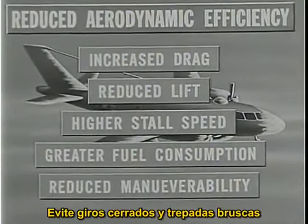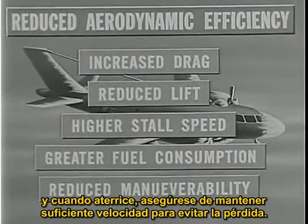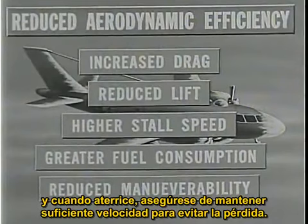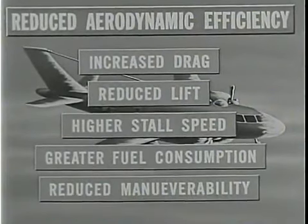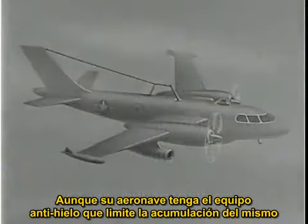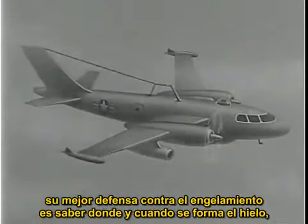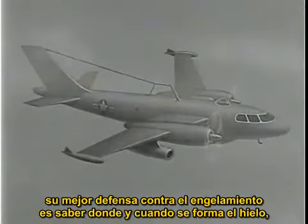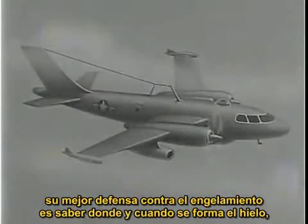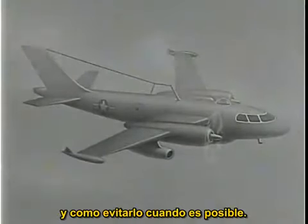Avoid steep turns and fast climbs. And when landing, maintain the power needed to ensure sufficient airspeed to avoid stalling. Even though your aircraft carries de-icing equipment to help limit ice accumulation, your best defense against ice formation on the aircraft is to know how and where ice forms and how to avoid it whenever possible.